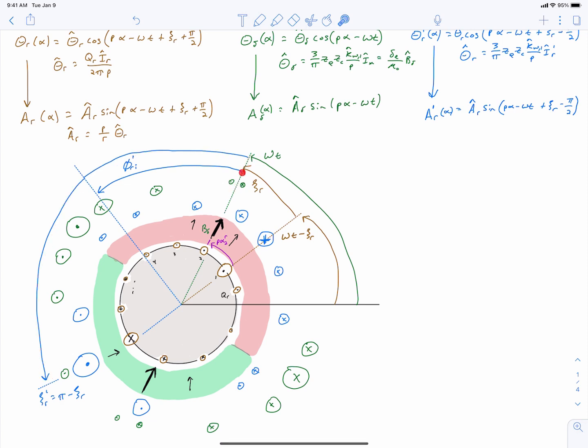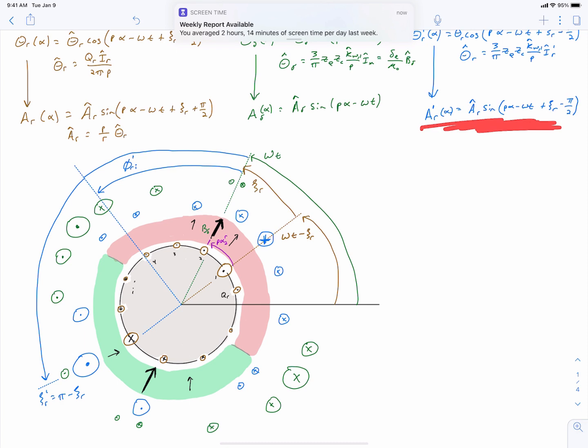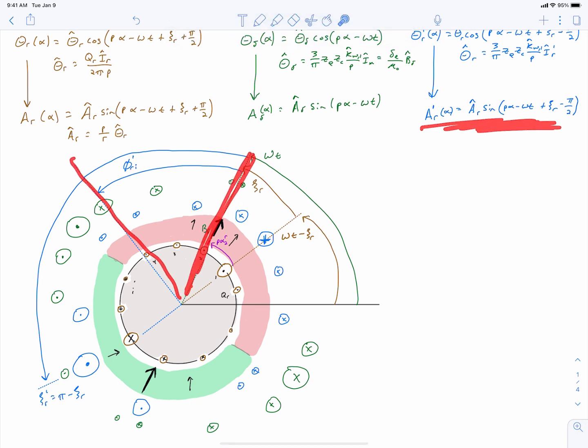And we can also define this angle phi RI, which is the separation between the axis of this current density and our magnetic field. So all this is set up to match the AC machine design sizing video. Moving further radially outward, we have our third current density, which is the magnetizing current density.